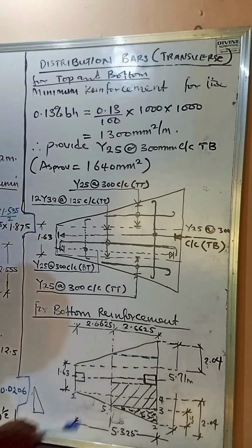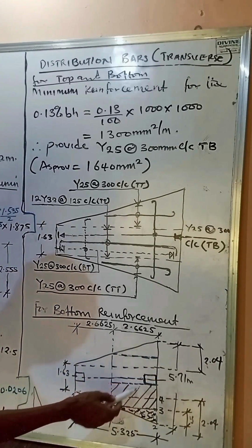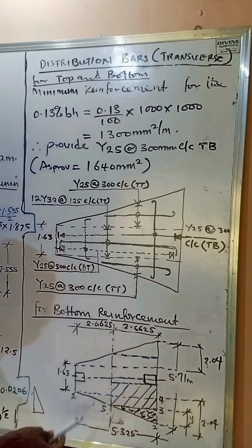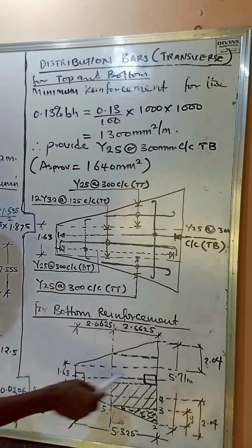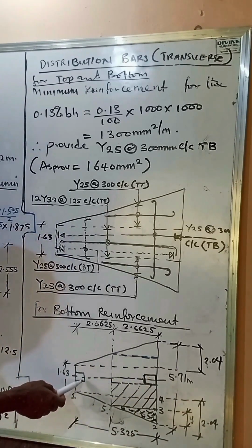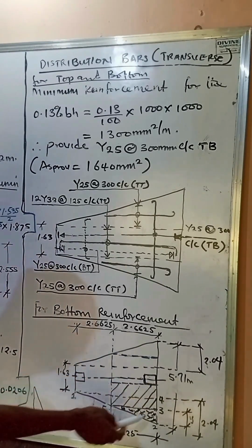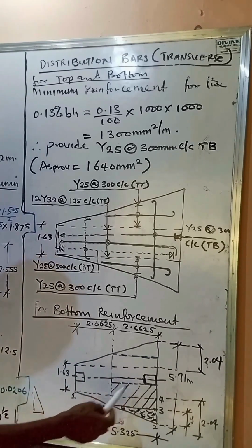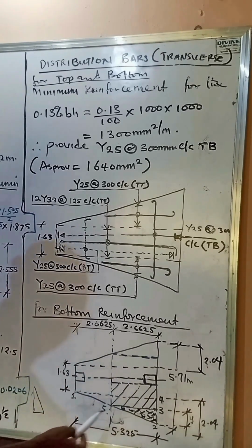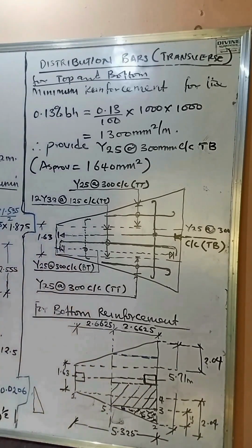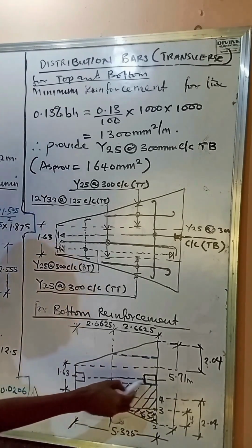All right. So if we take this particular portion as an isolated part footing, we are going to look for the moment of the pressure about the surface of the column, especially this column. So in this case, we are not going to treat the column at our left-hand side. We are going to deal with this at our right-hand side. So the whole pressure acting on this place, we know it to be 255.34 kilonewton per meter square. So this pressure will act on this surface. So we'll look for the moment it's going to produce about the surface edge of this particular column.